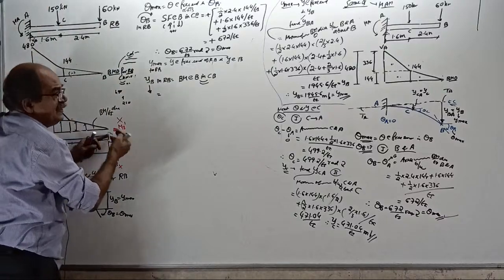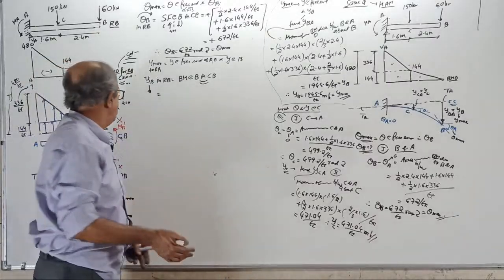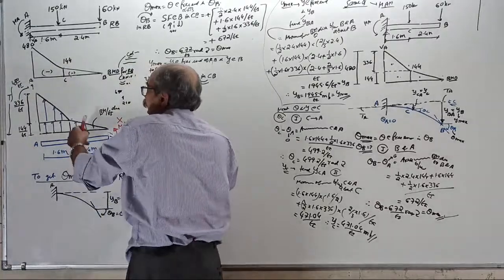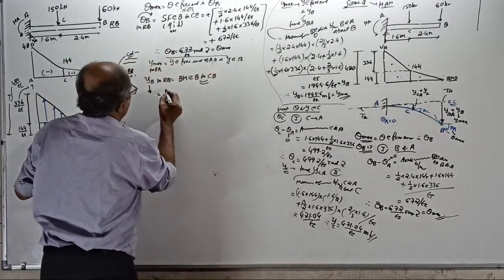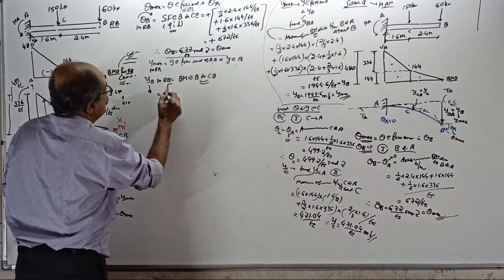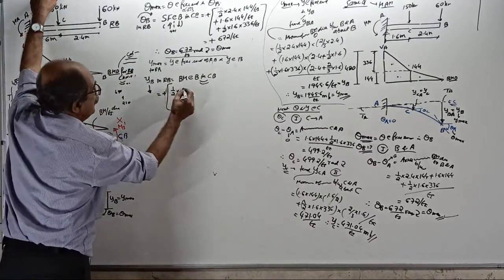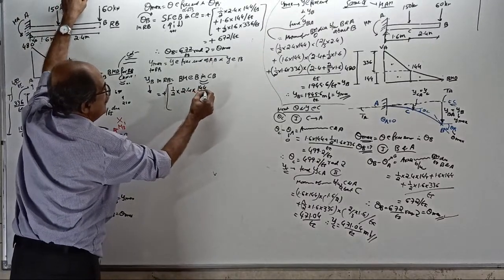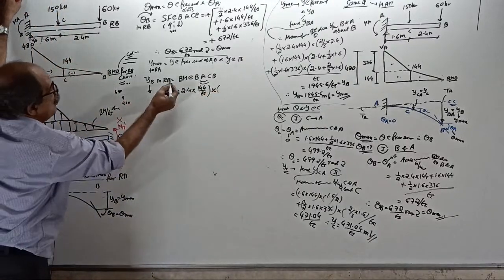Actually the bending moment is MB dash, but we don't calculate MB dash. Don't look at the fixed side, look at the free-hand side. Look at this side for the bending moment. See, all are sagging. This triangle, half, all positive. You can put plus outside if you want. Plus, half into 2.4 into 144 by EI is the total load into moment about B.